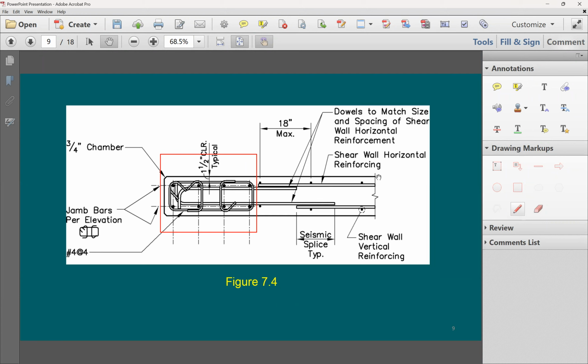If you recall, the shear factor equals 2 for one-way shear, and it's roughly about 4 for punching shear, which we call here two-way shear. Usually we say area of the concrete exposed to shear multiplied by square root of f prime c times a shear factor. Now, our shear factor in this case for shear walls is called alpha sub c. Here we go. Now, this is going to be our shear factor.